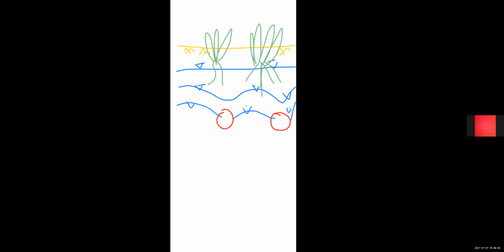So let S be the spacing between drains and D the depth of the impervious stratum from the center of the drain. Then the maximum height of the drained water table above the impervious layer is Y. So we can see this diagram. This is the root zone, water table level, ground level below the surface. Drainage is available here and here.